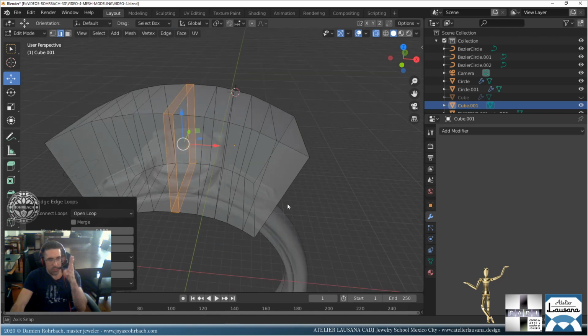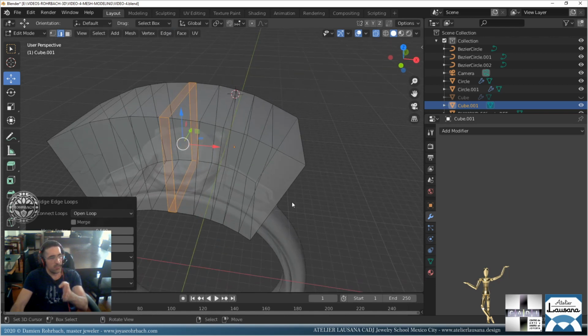Why? It's very important not to have the middle face, the inside face. If you keep it, you're going to have printing problems because you need to repair the mesh, and we'll talk about that way later on. But as a safe practice, remove the inside face. So that's why I didn't use the clipping function, because it's sometimes unpredictable if it's going to keep the inside face or not, and it's better to be safe.